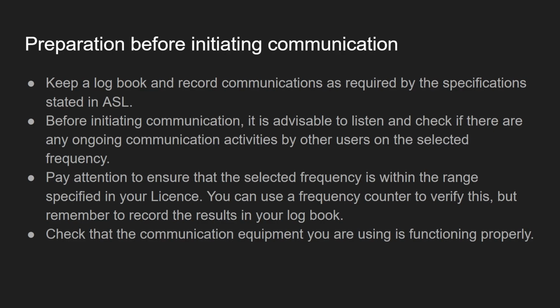Yeah. Preparation. Keep a logbook. As ASL mentioned, you should always keep a logbook if you are using a fixed station, a fixed location radio. So before you start the communication, you should turn on the radio and make sure that this channel is not occupied yet. There is no one talking in this channel. You can listen for like 30 seconds to a minute. Make sure no one is using it, then you can start CQ.